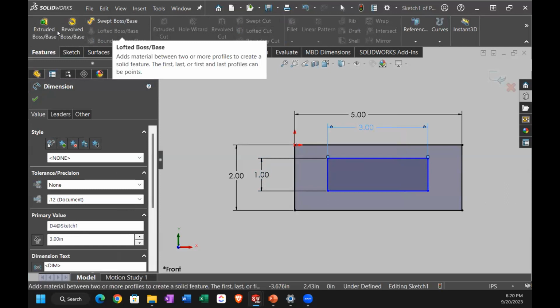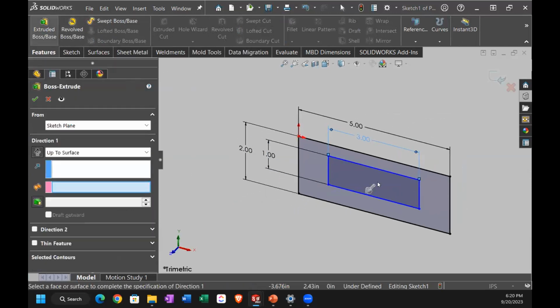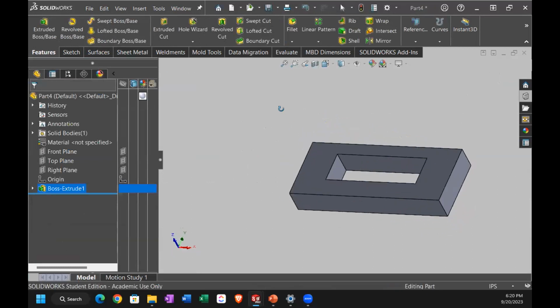Okay, so when I go into the extrude, give it some distance. That's going to be a little bit long for a 1/4 inch end mill, so keeping it at about 0.75. And did I accept, or am I just waiting? There we go. All right.